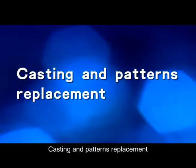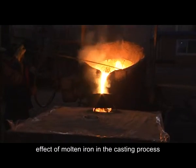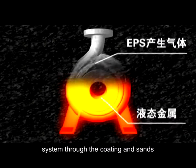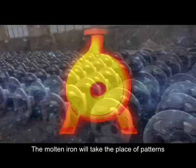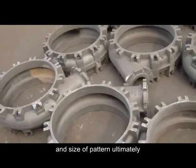Casting and pattern replacement. The EPS pattern will gasify due to the heat effect of molten iron in the casting process. The gas enters into the negative pressure system through the coating and sands. The molten iron will take the place of patterns. The castings will ultimately form with the same shape and size as the pattern.